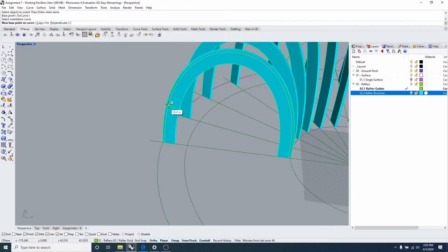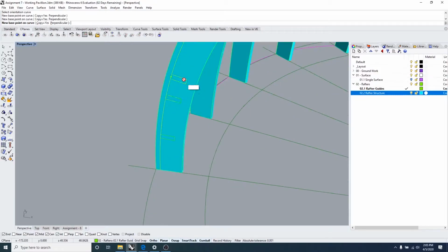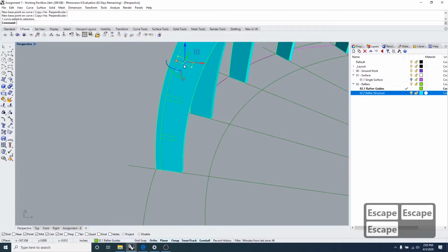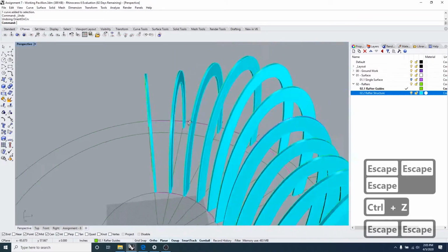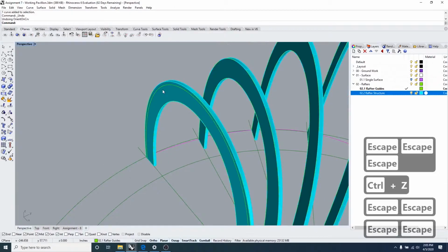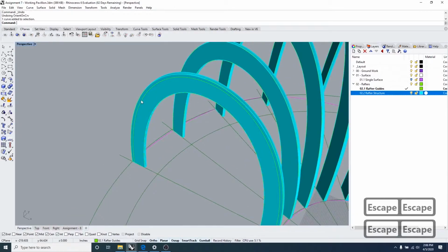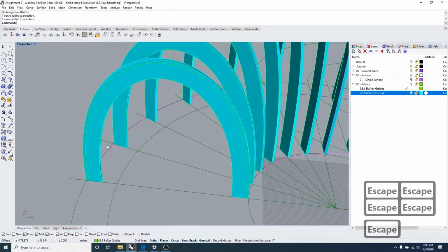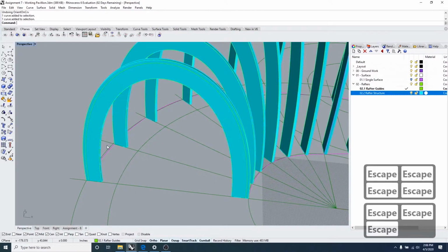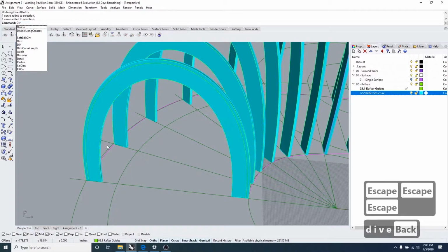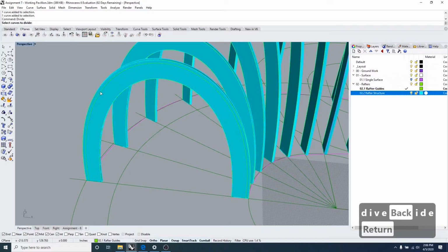Now we need to have 9 objects in here at equal distances, which we haven't done. We only have the curve and the profile. We know it's going to work because we can copy it around, but we don't know exactly where. So let's figure that out. I'm going to undo one time. And I am going to say that I want to divide this curve in 10 equal segments. And the way we do that is by using a command that is called divide. And we select the curve that is our guide.